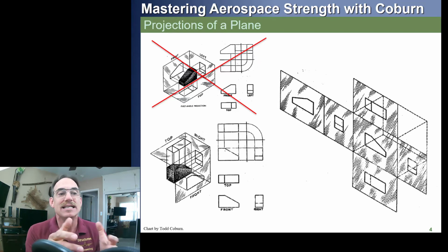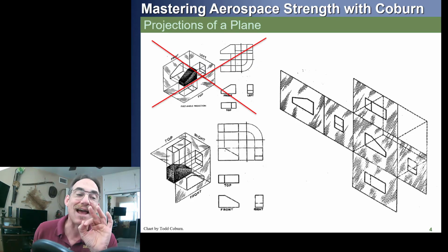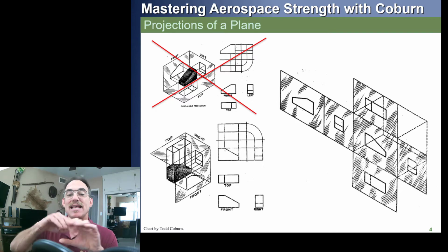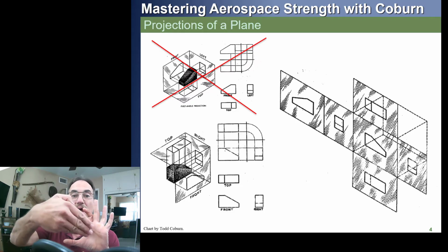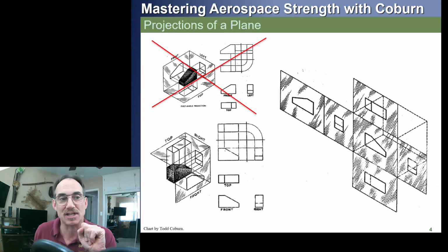Each of those flat sketches will be drawings of how the part looks through that plane. Any parts that we can see, like fold lines, will be solid. Any that are actually there but that we can't see, because they're beyond the part, will be shown as dashed lines.